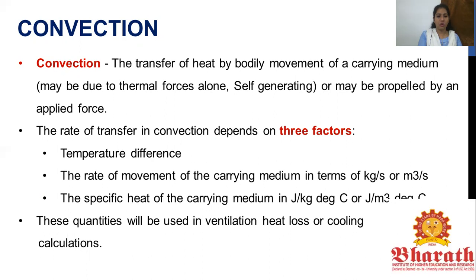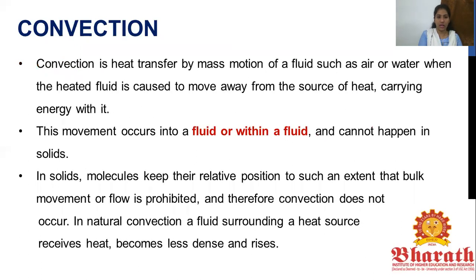So talking about how all of these things are actually very important elements in calculating your ventilation figures or your cooling calculations. Convection is a heat transfer by mass motion of a fluid, such as air or water, when the heated fluid is caused to move away from the source of heat, carrying energy with it. This movement occurs within a fluid and cannot happen in solids. In solids, molecules keep their relative positions to such an extent that bulk movement or flow is prohibited.